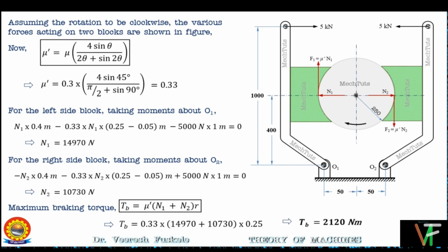So this is how you can do the analysis of double block brake. I hope you have understood the method of taking moment about point O1 and O2 and then how to calculate the braking torque in case of double block brake.